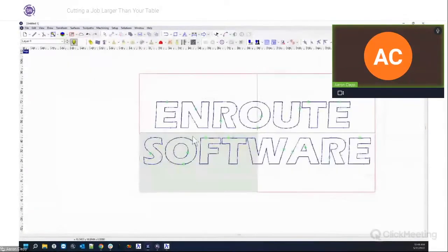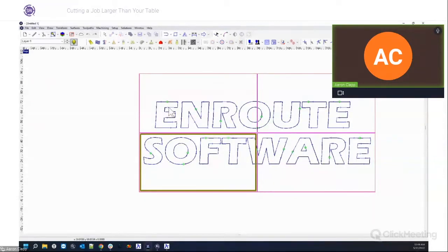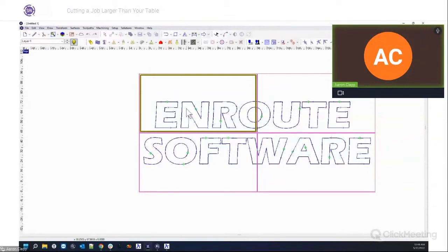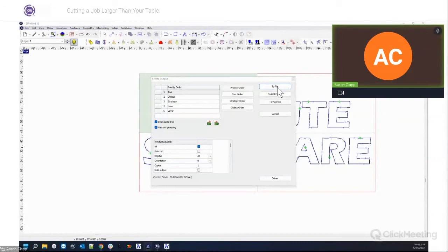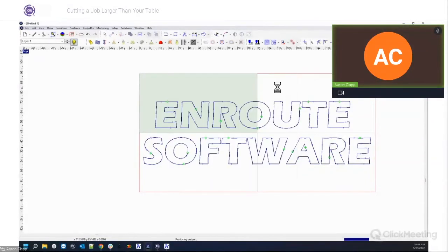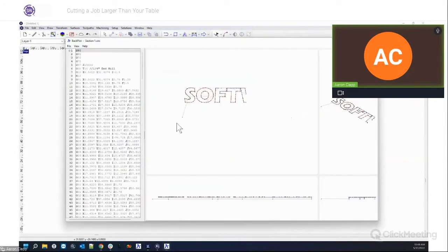So that's great. Now let's go back and let's change our panel. So all we have to do is click on Define Panels. It leaves all of our panels in place, so we don't have to worry about every time we click that. It doesn't change them. We'll click on this one, hit Enter, and we'll just output again. This will be section 2. And then we're going to show something here in just a second as to what happens when you don't choose that option for plate. So let's hit Open. And we'll go to section 2.